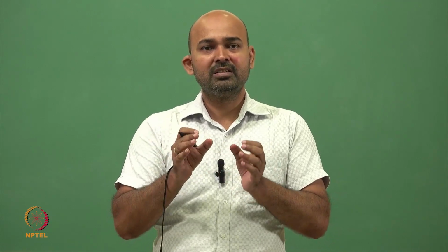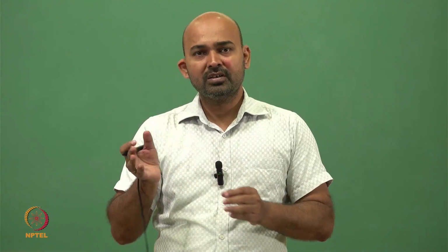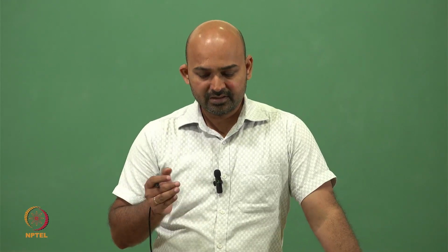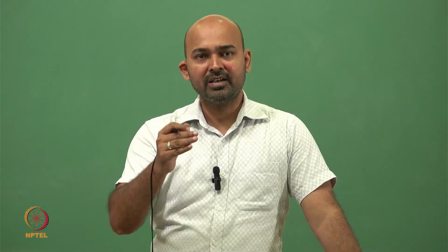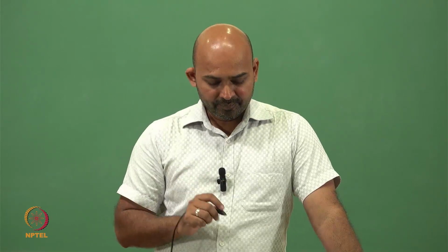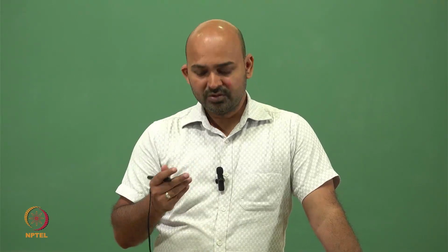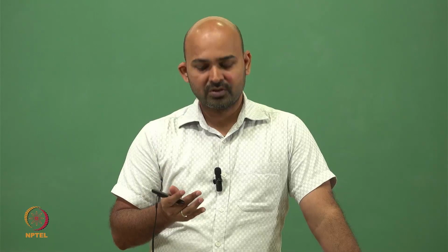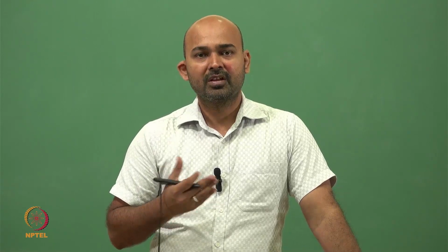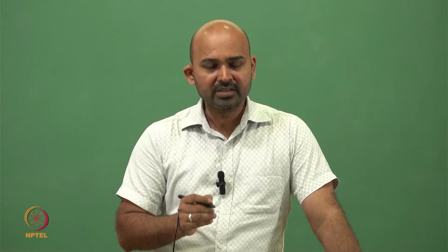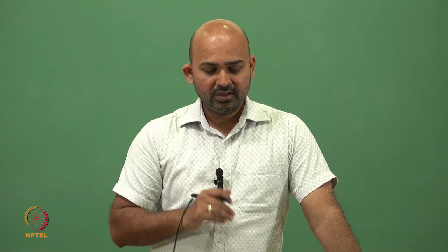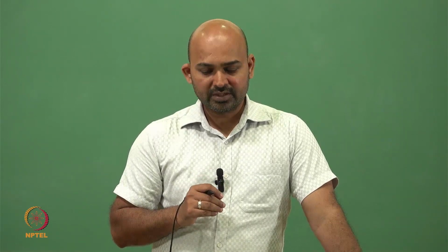Delay 1000 means 1000 milliseconds, or 1 second. The program will wait for 1 second before going to the next line. Millis is the function which is used to get the current time in the program. So these are some basic functions which are used for programming in Arduino sketches.